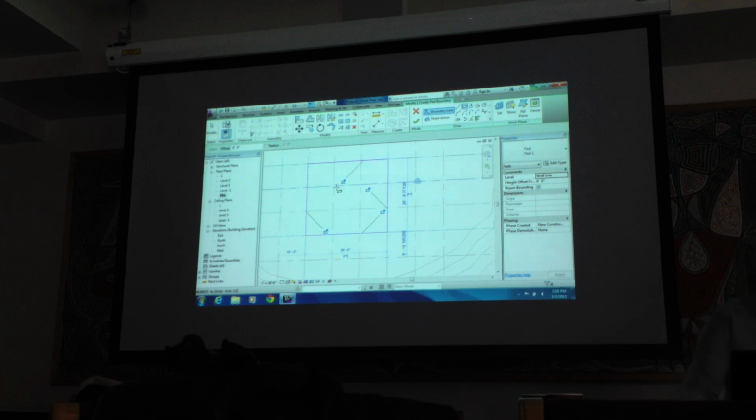So usually it's a good idea to lock it if you want to do any future changes. It's kind of like set in point and it's working with the grid line. So if you want to change the whole building, you can just change the grid line and the rest of the building will follow suit. So you hit lock on the lines that you want to actually be locked. But if you know you don't want something to change, even if you accidentally screw up, you can just hit unlock and it won't follow the grids if you change the grids or any other part of the building like the walls.